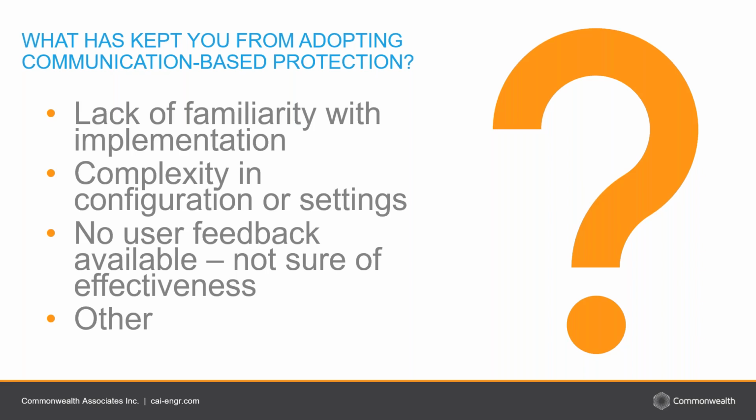Before I move to the next slide, however, I just want to talk about the implementation details that we're presenting. So as I said in the beginning, with many things, there are multiple ways to implement 61850 into your protection and control designs. So we're covering some high-level basics from a hardwired versus network standpoint, and covering some solutions or ideas for documenting those interactions that are now taking place digitally. Before, if you're a protection and control person, you pull out a DC schematic.